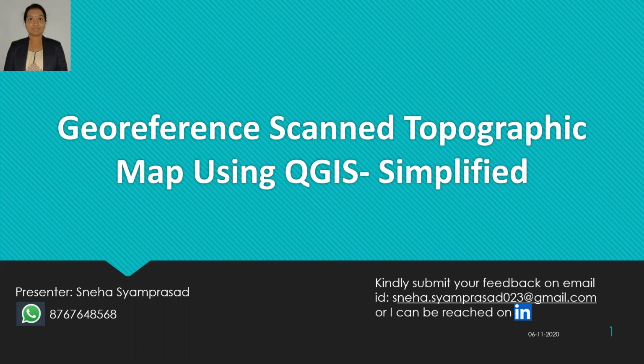Most GIS projects require georeferencing some raster data. Georeferencing is the process of assigning real-world coordinates to each pixel of the raster. Many times, these coordinates are obtained by doing field surveys, collecting coordinates with a GPS device for a few easily identifiable features in the image or map.